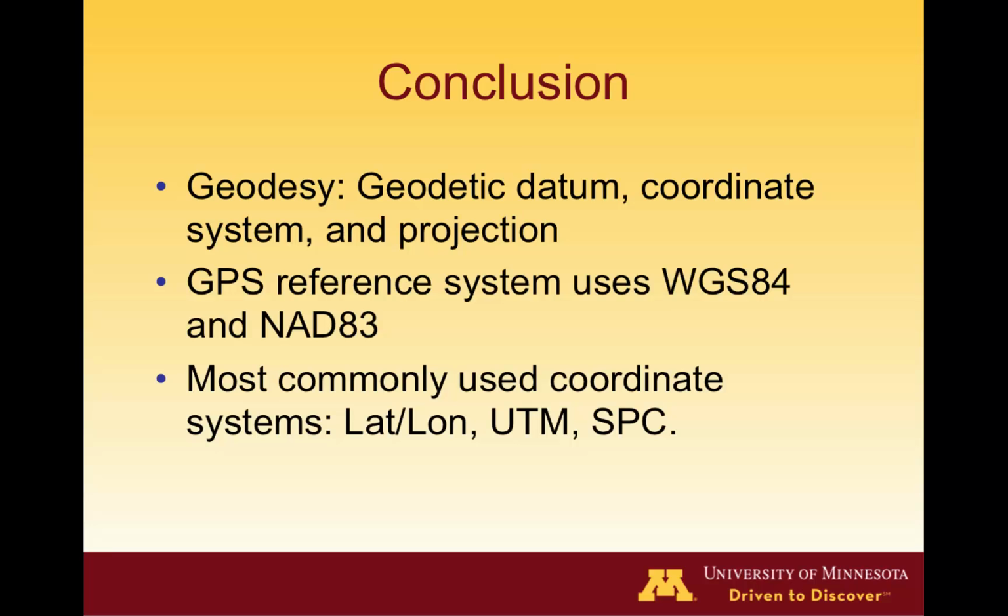You want to remember that the UTM divides the Earth into many grids and does projections based on these local grids and tries to avoid a lot of distortion from projection. And in that sense, the UTM needs projection, and the latitude, longitude, and height system does not need projection.